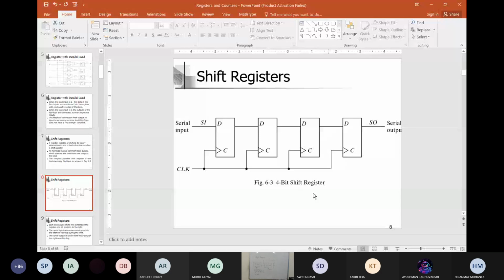So can I say this is a shift register? In fact, more than a shift register, just check whether it's serial in and serial out. Because I am not counting the intermediate outputs. There are 4 D flip-flops. I have D, another one, another one, and another one. I am only connecting them like this and collecting at the final output only once. I am not collecting intermediate outputs.